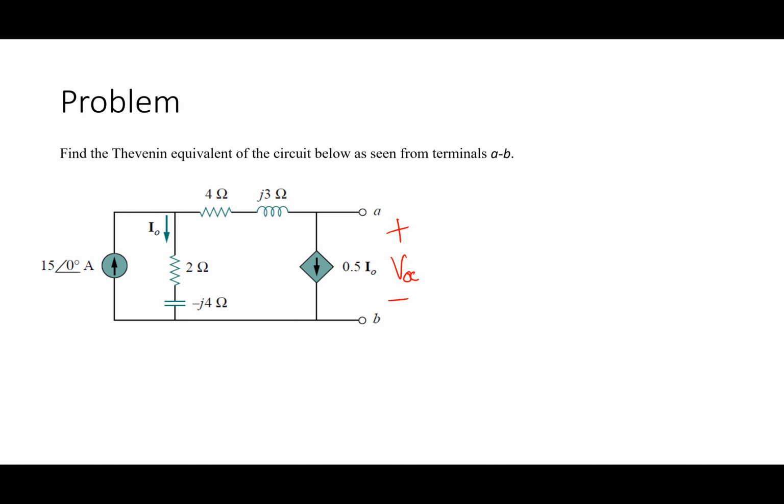If I look at it this way, I would do exactly what Stephen said, and I would simplify this down. So I'm going to have two impedances, Z1 and Z2. Especially with capacitors, they get a negative in their impedance. So I've got negative 4j. What does negative 4j mean? Why do I have a negative? That's weird, isn't it? What does a negative sign mean? The angle is negative 90 degrees. That's all it means, right?